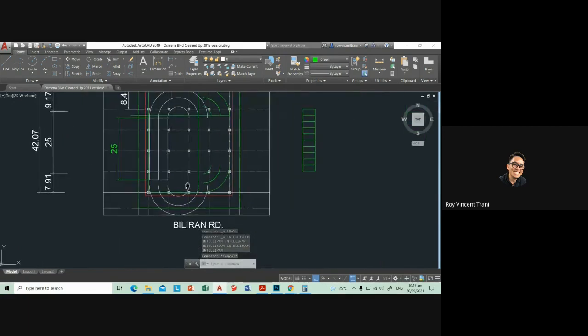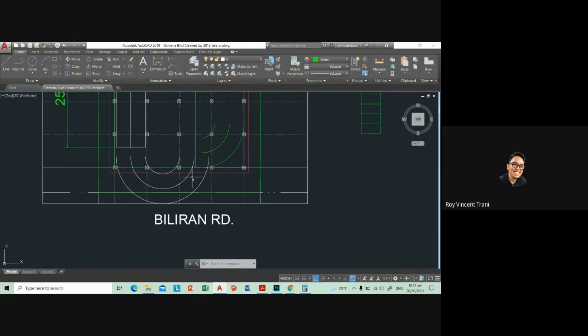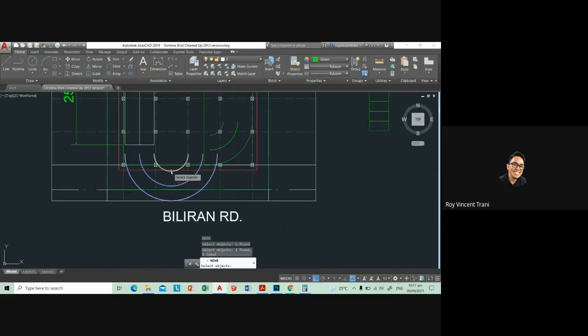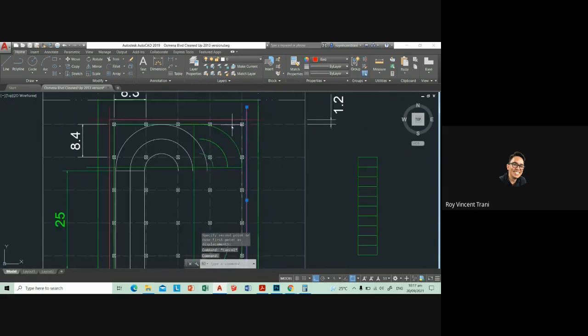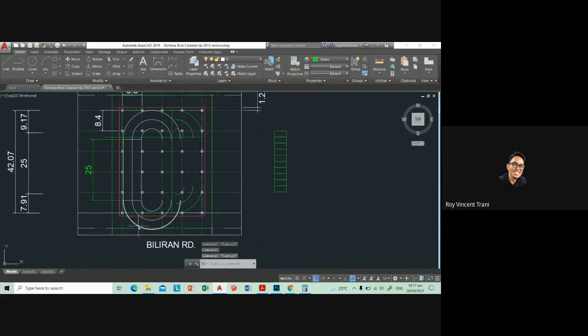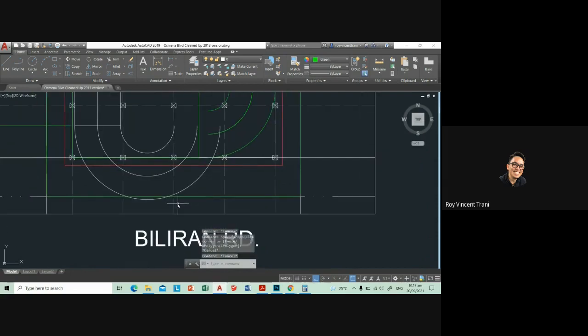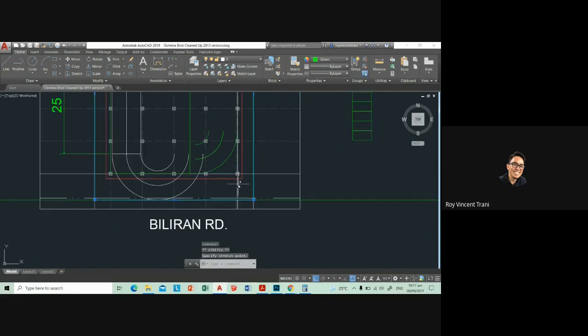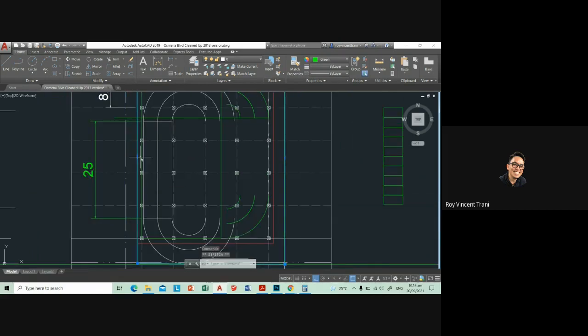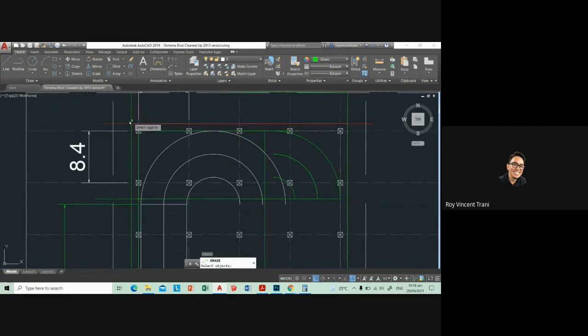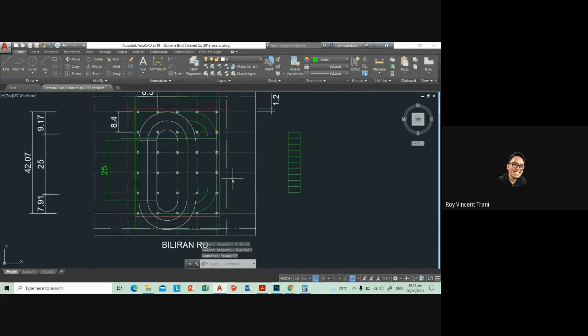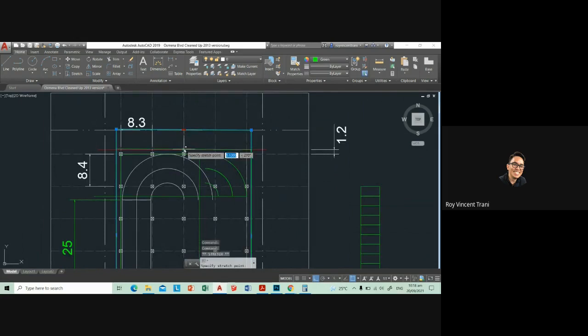Let's see. So this works now. I have to build all the way out here, so maybe I can go a little bit closer. In red is the ground floor building footprint, and in green, this will be the basement boundary. Then I don't need to extend all the way to the sides. I can just follow the ground floor footprint, and now my basement looks like this.